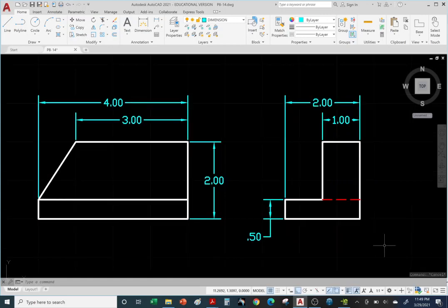All right, so another thing I wanted to bring up is decimals. Obviously, this is inches. One way you can tell a drawing, you know, whether, hey, is this inches? Is this millimeters? How can I tell? Well, you can tell by the small numbers, right? If it's millimeters, you would see 30 millimeters, 50 millimeters. Another way to distinguish from a millimeters drawing is to look at the number smaller than 1.